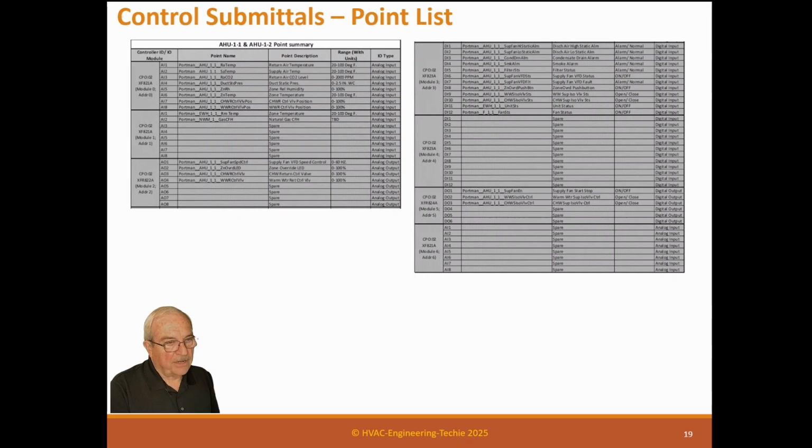We have standard sequences. The control manufacturer has standard sequences. ASHRAE Guideline 36 has standard sequences. And as an engineer, you should always stay with standard sequences. You do not need to create an exotic sequence.